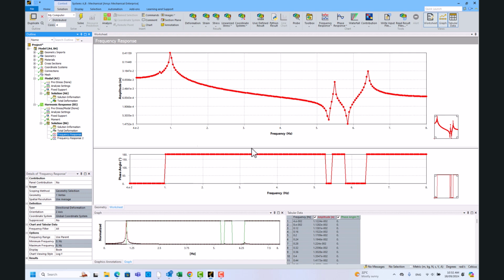I have to note this plot is slightly different to what we get from the sine wave sweep in experiments, because this is always steady state, but in the experimental sweep test, the system might take a bit longer to get into the steady state, and therefore the peak is not as sharp. Also, the phase change is affected by the damping ratio that exists in the system, which we haven't modeled yet. So this is the ideal case.